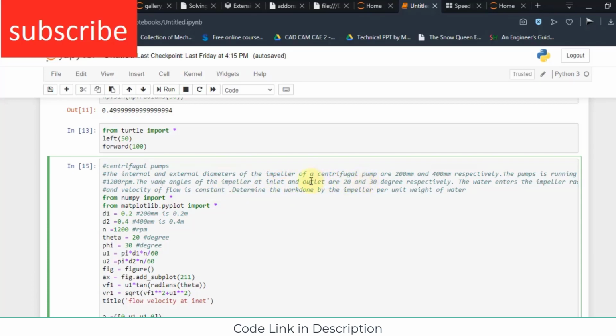Remember, the vane angle at the impeller inlet I am representing by theta, and the vane angle at the outlet I am representing by phi. The water enters the impeller radially, so it means that alpha is equal to 90 degrees and the velocity of flow is constant.